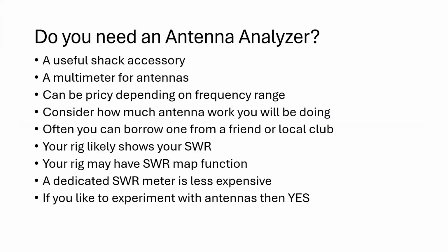All right. So, do you need an antenna analyzer? I will say it's a useful shack accessory. It also can be used outside of the shack. As I mentioned, you could call it the multimeter for antennas. A disadvantage, it can be pricey depending on what frequency range you want to cover. And you should consider how much antenna work you're going to be doing.